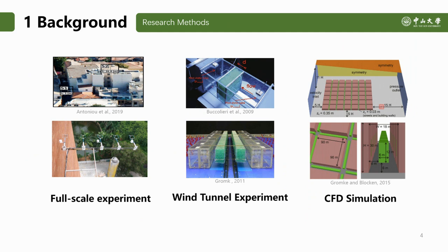The main advantage of CFD simulation is the ability to perform parametric analysis and provide high-resolution computational results. However, the idealized boundary conditions and simplified physical process may cause simulation uncertainties, resulting in compromised numerical accuracy. Therefore, further high-quality experimental data are necessary to validate and improve the numerical simulations.